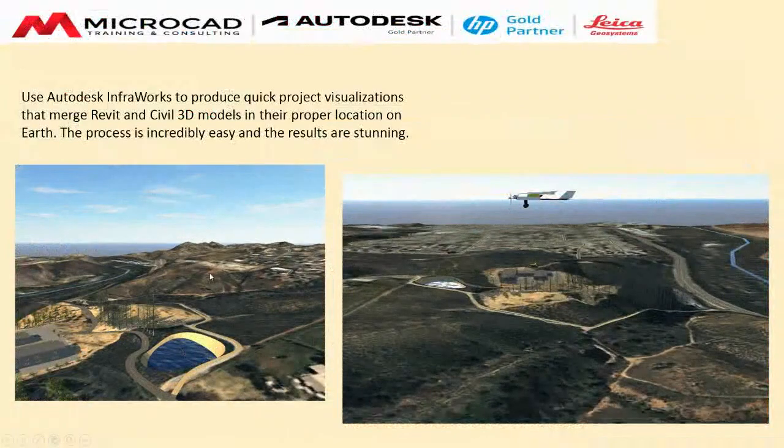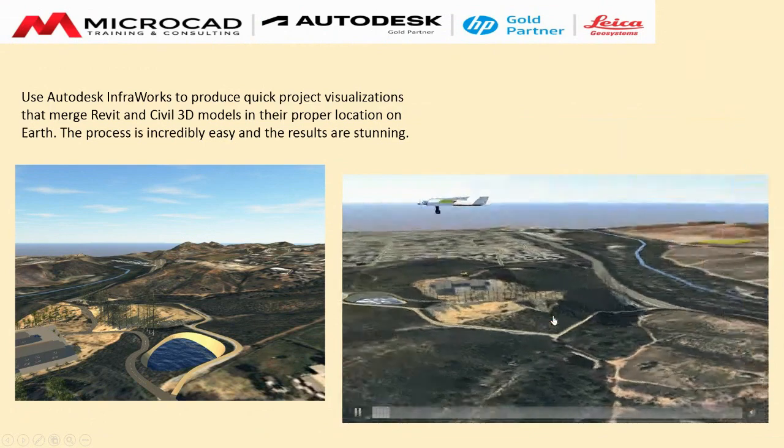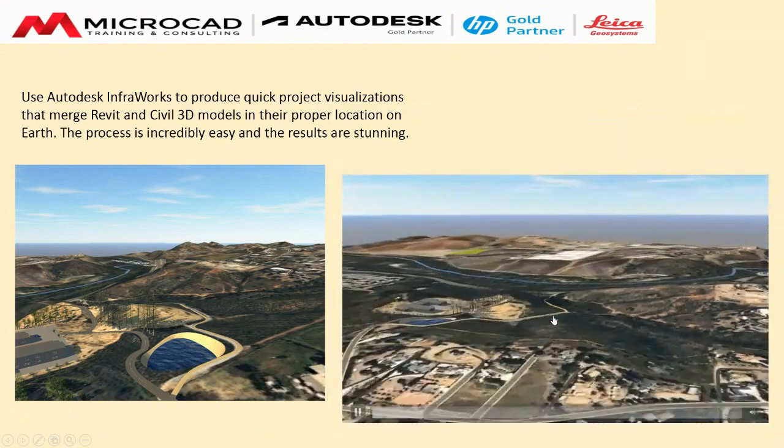Okay. And then what I did is just went up into a 3D view, took a snapshot. You can see the building, you can see a pond that we added, a couple of different roads, stands of trees that we added as part of InfraWorks. And then here's a fly around animation of the site that was created with InfraWorks.